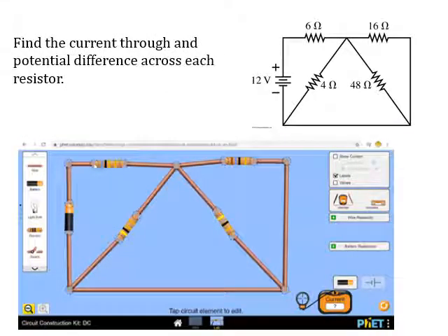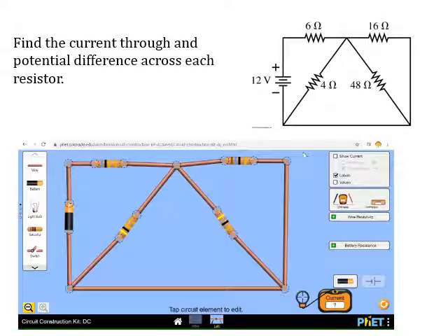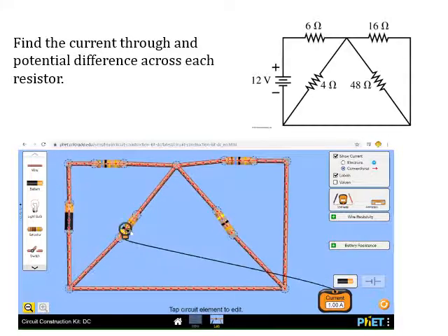So now, I said as we worked through the problem that the 16, 48, and 4 ohm resistors were all connected in parallel. I'm going to run through a PhET simulation now that also shows how they're in parallel. So here's the original setup, and I'm putting the ammeter on to show the currents. If things are in parallel, you're used to seeing them a certain way in a circuit diagram.